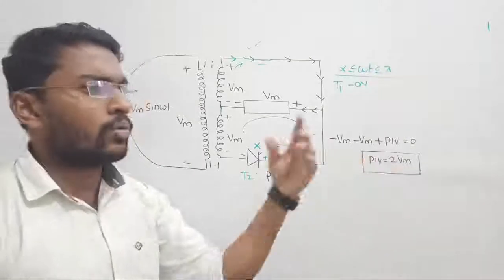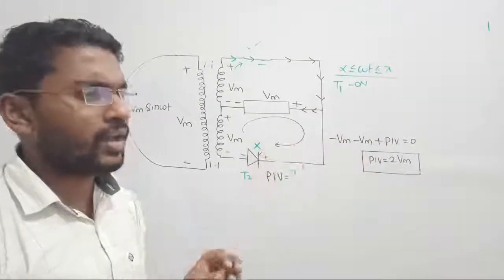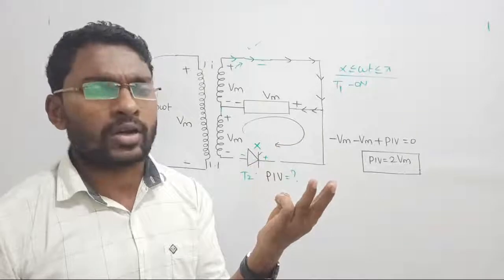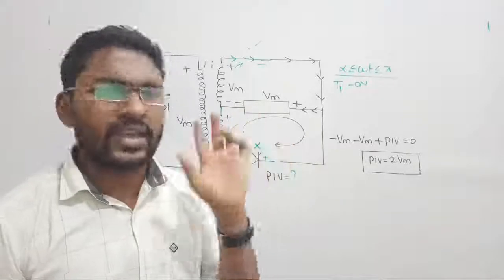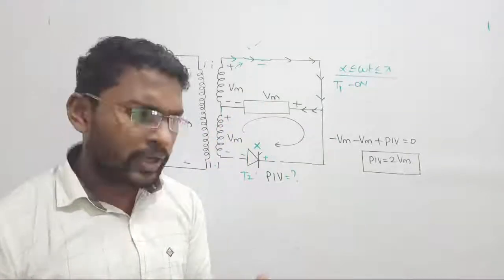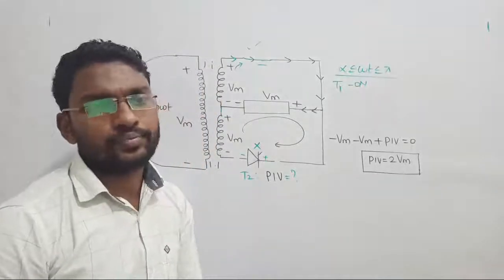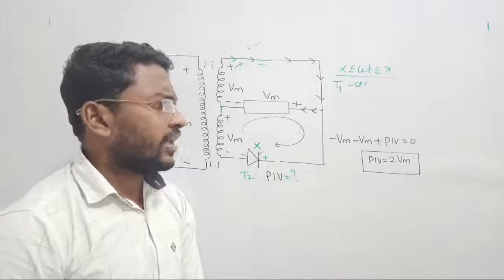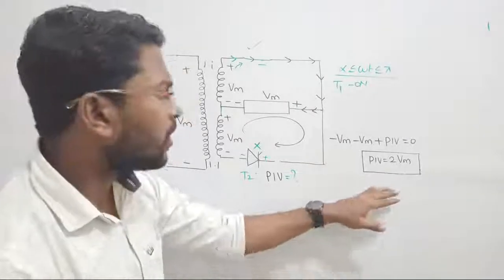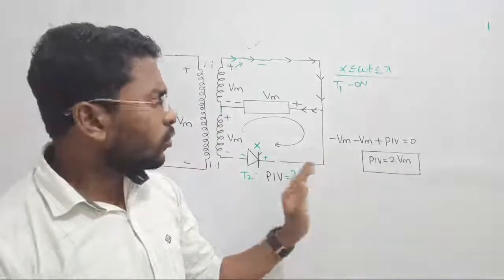Whereas when I am talking about the full bridge rectifier, there is simply no need for a transformer at all. I need 4 thyristors with the same supply voltage, Vm, because the peak inverse voltage across the thyristor will become only Vm, not twice Vm. Conclusion: the highest cost is the simplistic drawback here. This is the only difference.